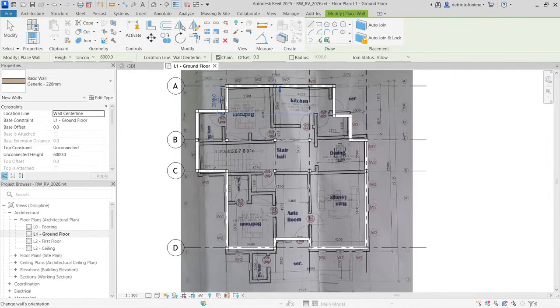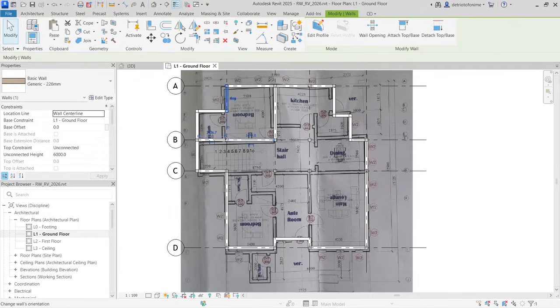The next thing we need to do is to create the internal walls themselves. And we have one coming down from here. Thanks to the grid, we already know the measurement of each one. So you can have this wall this way and connect this one to this other beam here. Press escape twice. You can select this wall.